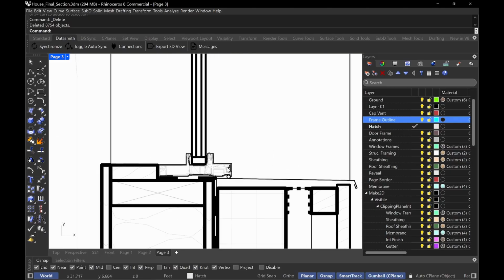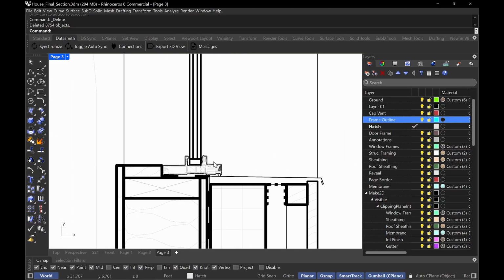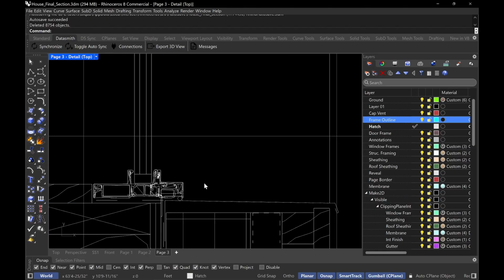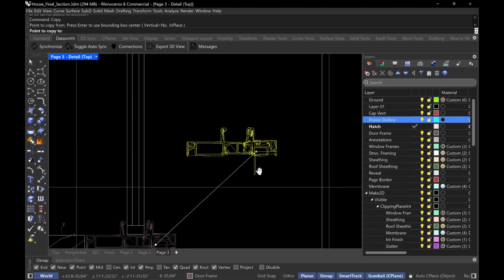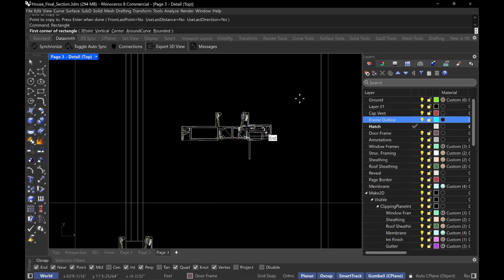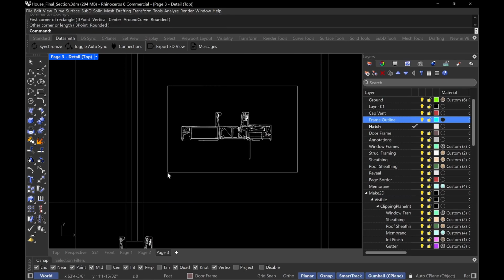And a really good way of doing that is the curve Boolean command. If you want to do these thick outlines over things real fast, over complex things, I do curve Boolean. So let me double click in here. I'm going to copy this frame like this. Up here, I'm going to do a rectangle around that, and then I'm going to do curve Boolean.